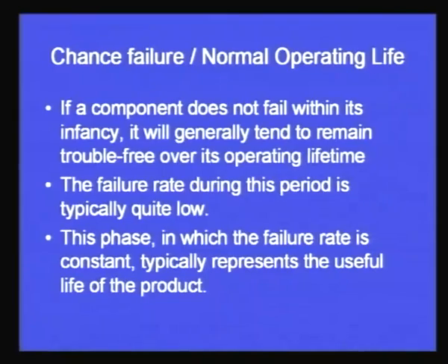So, failure rate is high in the infancy stage, it is very low in the chance failure or the normal operating life. So, this phase in which the failure rate is constant typically represents the useful life of the product. This is basically the useful life of the product for which it has been designed.